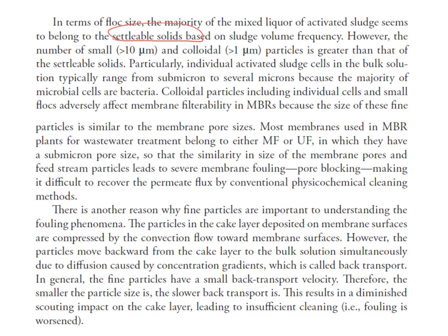And if you look at the volume particle size distribution, the larger particles exist most in the mixed liquor. However, the number of small particles is greater than that of the settleable particles if you just look at the number. So that's why we have to look at the relative importance of the small particles.